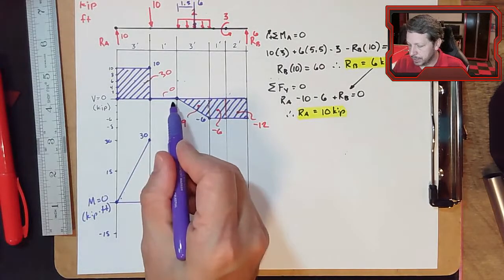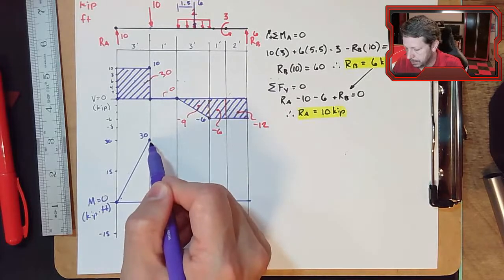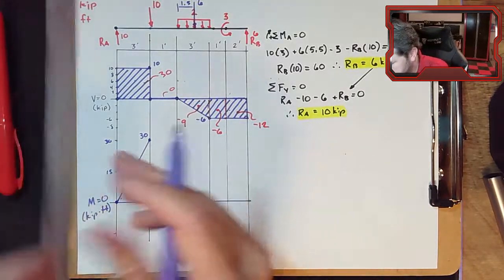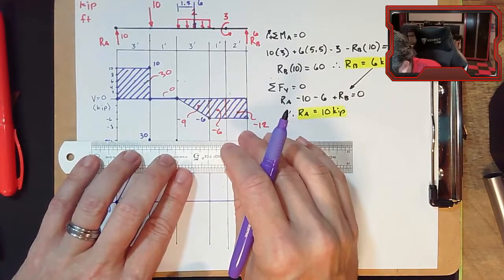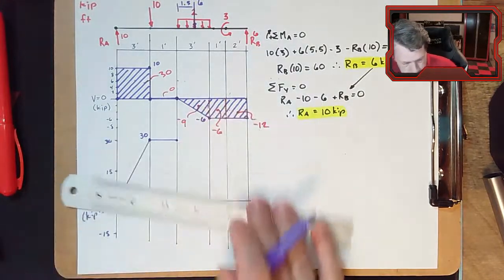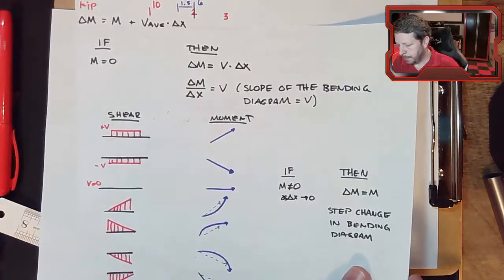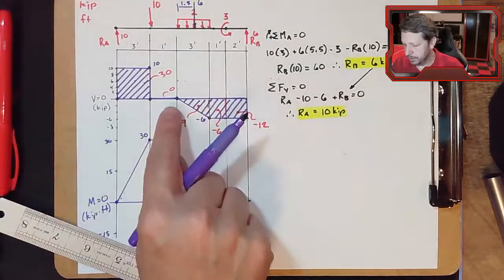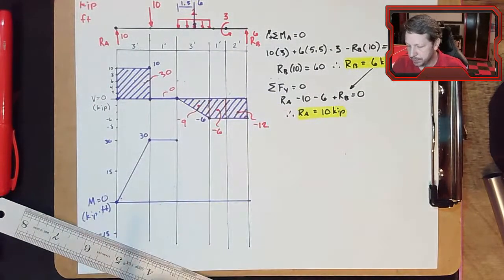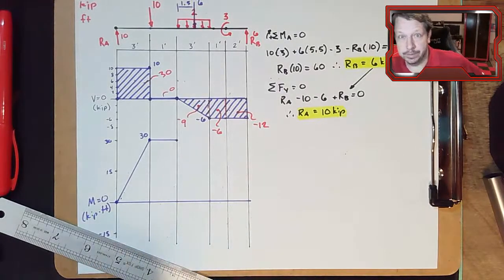This is the unusual section where we actually have no shear, no concentrated moments. So in this little section, there's no change in bending moment. So it's just horizontal. That was this one. It's just horizontal. It's not common because most of the time your beams don't have sections with 0 shear in them. I've arranged this one so that it did, but they don't often even do that.